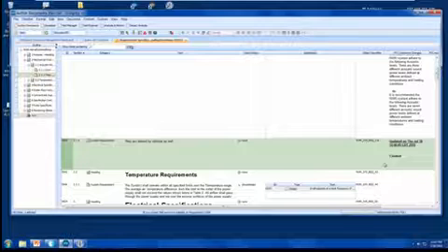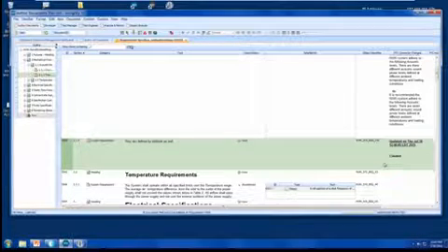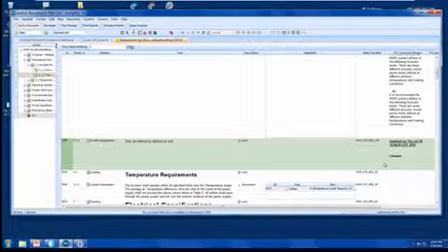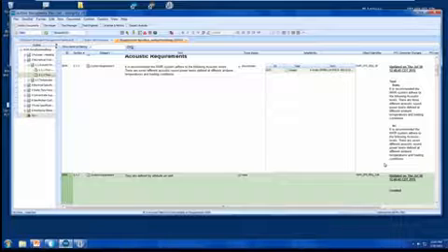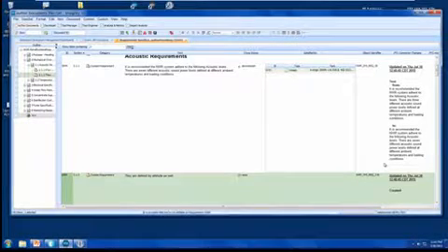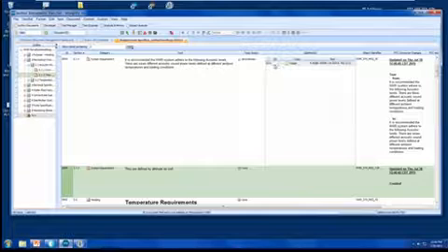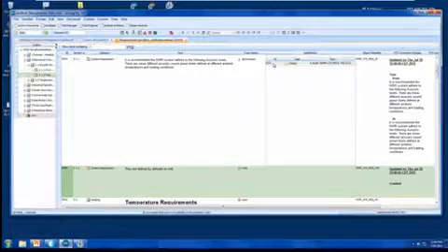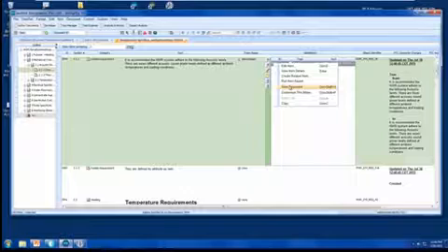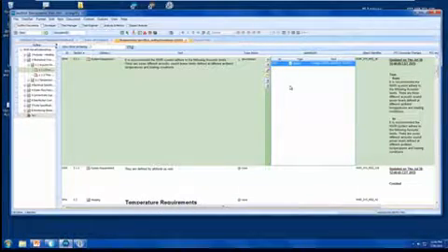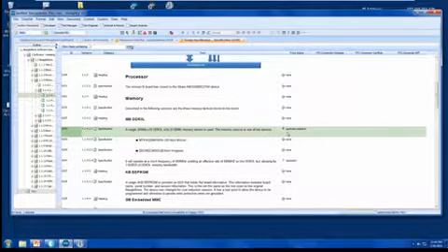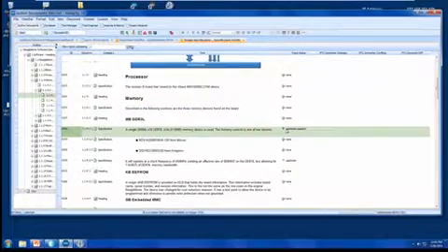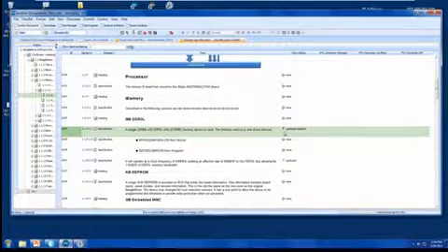Well, me as business partner B, or the supplier in this scenario, say, well, there's some changes here, and I as the integrity engineer need to go in and rectify some of these changes. So to do that, I'm going to go down to my software level requirements. I'll just navigate down from the one that's changed, and it navigates me directly to the requirement in question. We'll see that I've got a suspect link upstream, which is what I would expect from a good requirements management system: if something changes on either end of the traceability link, it gets suspect.